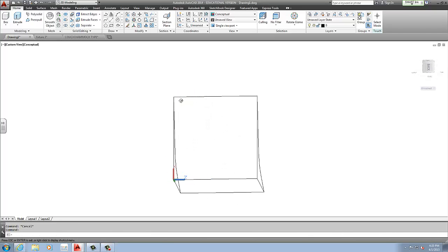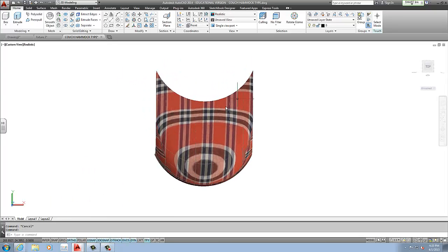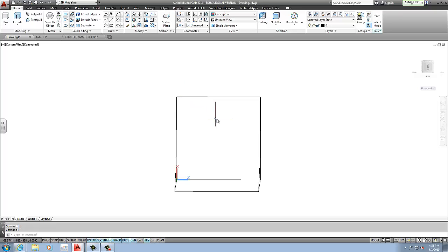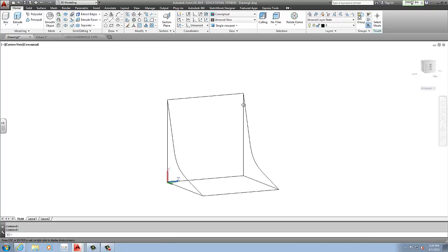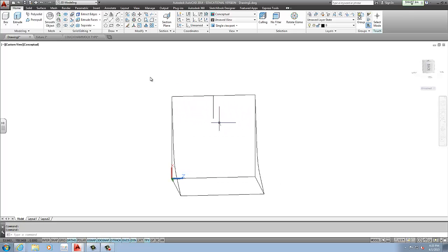Finally, to adjust the top, to make it a curve here, I can also again use spline, or I can use an arc. The tricky part about this one is I want to make it a nice consistent point at the center. So I can use a reference line based on the center point or midpoint of that horizontal line. Using ortho, I can move down, giving me a third reference point.